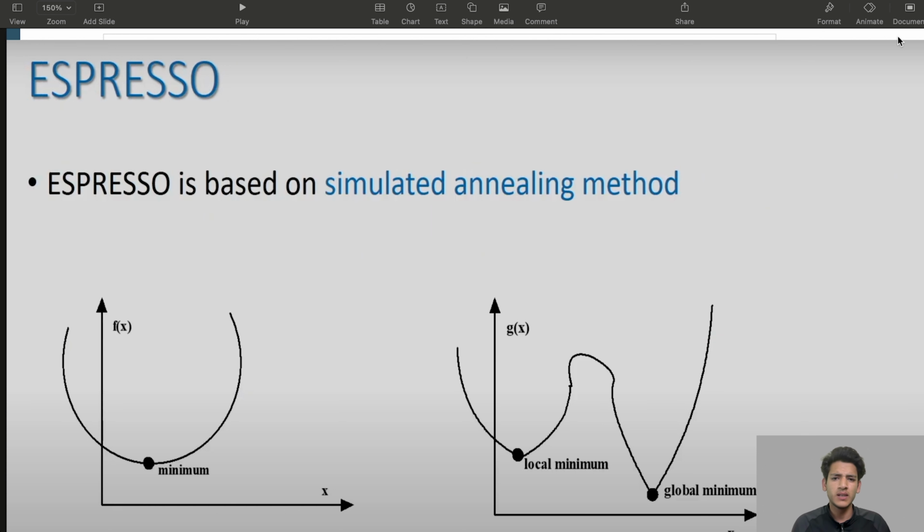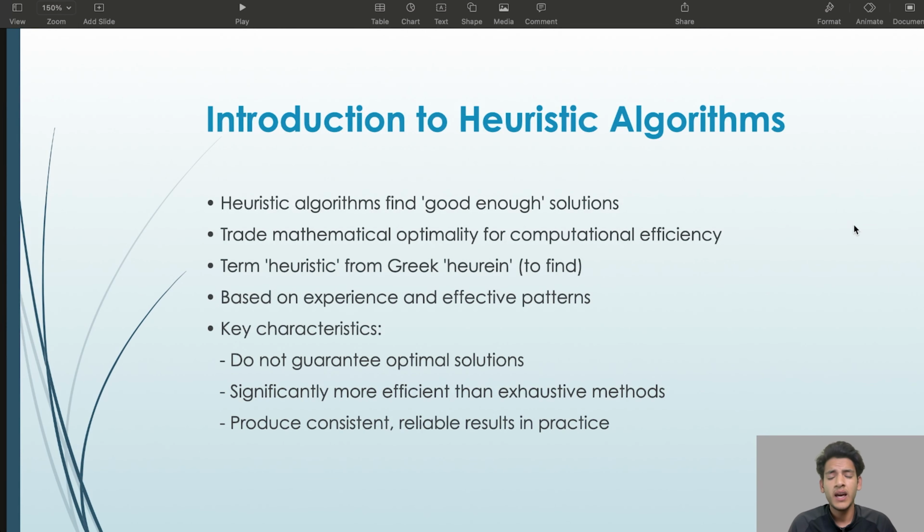It first starts from an initial cover, like a very basic implicant, and then it covers the prime implicant by traversing in different directions. Like if you have three variables, first you look at a variable in y and traverse in different directions, like in the z direction or y direction, and look for a local minimum point. You have to do this in an iterative manner and look for the global minimum point where you can minimize your Boolean function. As we know, our Espresso algorithm is heuristic in nature.